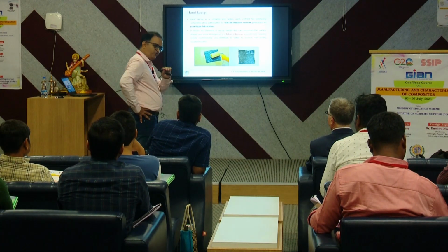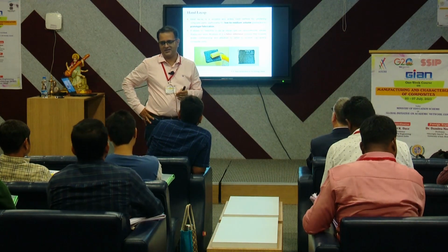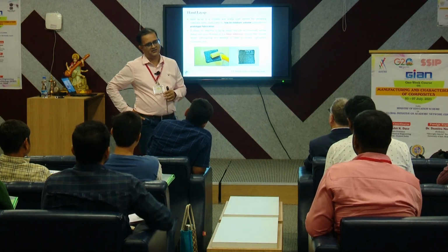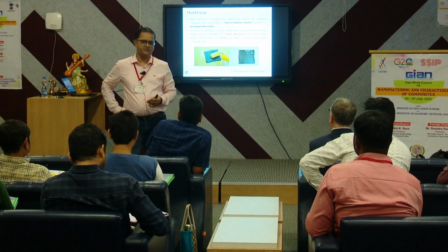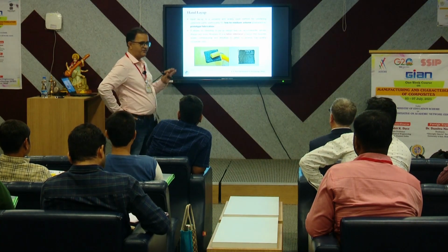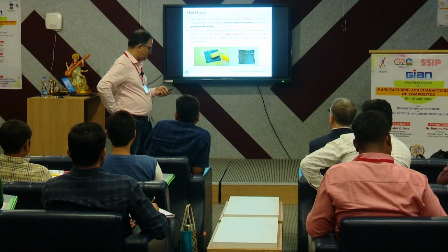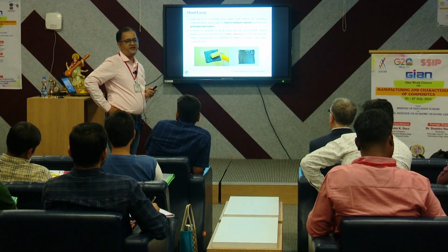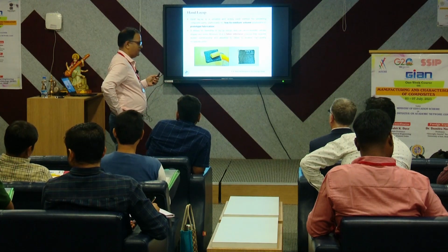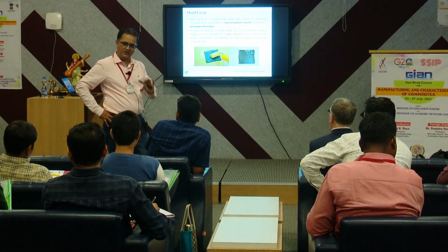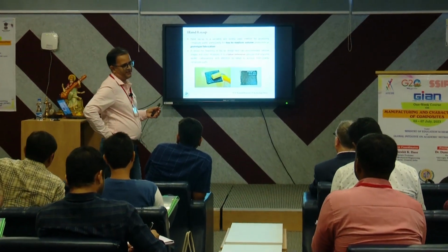Okay, so a few of the processes which I want to discuss may at some time or other have been of interest for research at our place or in some of our research teams, here or somewhere else. So, those processes which I feel are of relevance, I have included. The most elementary process is the hand layup process. Very simple process. As we saw in that graph, we go for lower volume of materials here, we get lower production, and mostly it is for prototype fabrication.